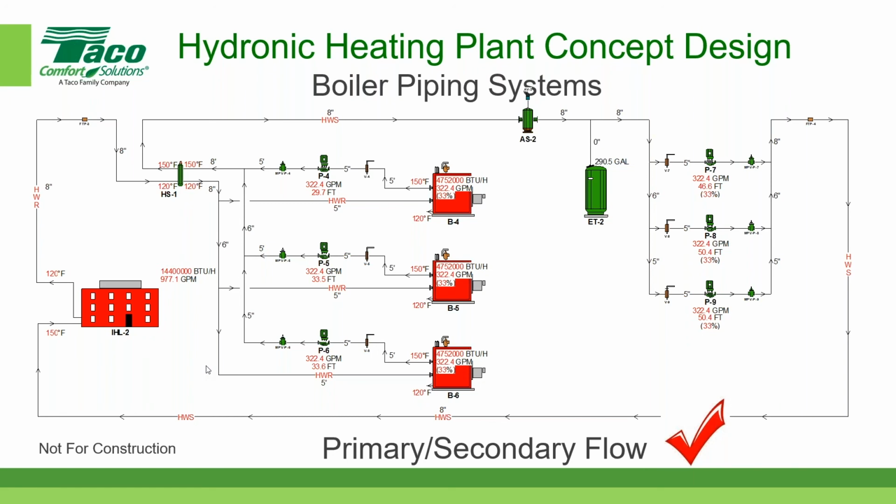The Delta T, what would your general recommendation be? I see 20, I see 30, I see 40 for a heating system. Do you have a rule of thumb number that you're used to? Well, again, Delta T becomes a function of the terminal units in the building. The higher the Delta T, typically the more surface area that you need in order to accomplish that Delta T, and so the more expensive the terminal device. So now it becomes engineering economics.